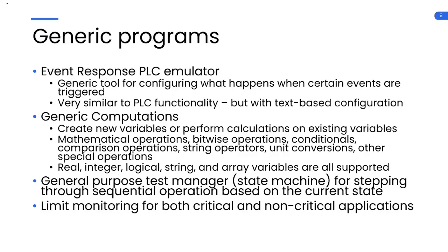Quick note on units. So CyFlex is going to use standard SI units for all its calculations. So even if you create a variable and you say you want it to be in units of Fahrenheit, we're not going to do those calculations in Fahrenheit. We're going to convert to base SI, do the calculation, and then convert back to Fahrenheit for your display purposes.